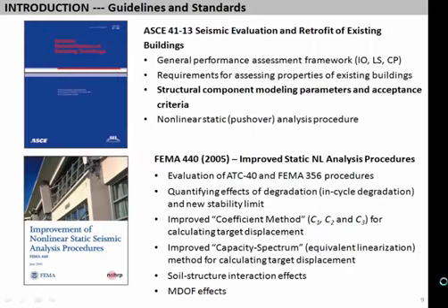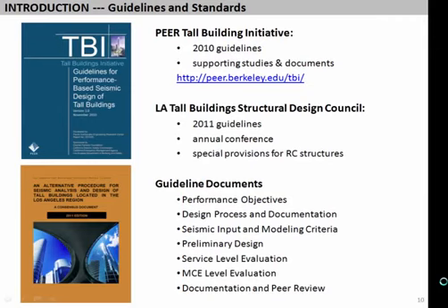I think we should keep in mind that ASCE 41 really was developed thinking about rehabilitation of existing buildings. Also, pushover analysis is really focused towards that. And while there have been improvements in pushover analysis through the years, some of the modeling criteria have not advanced dramatically, in my view, in ASCE 41. And I think that's where we're starting to use nonlinear dynamic analysis in tall buildings, where we're trying to push it, and documents like ATC 72 provide additional information there. So it's really these tall building documents that might be embraced, going from static pushover to nonlinear dynamic analysis.